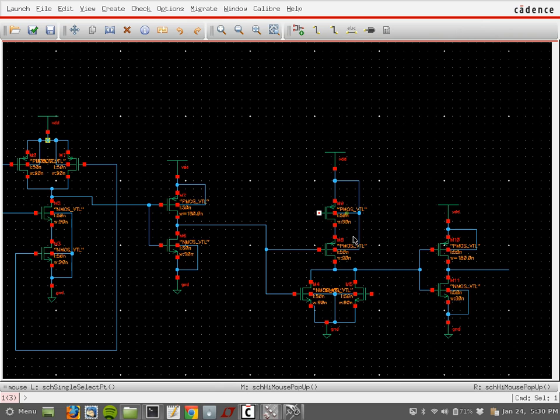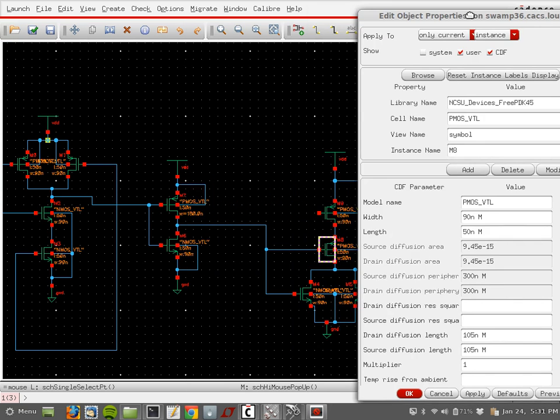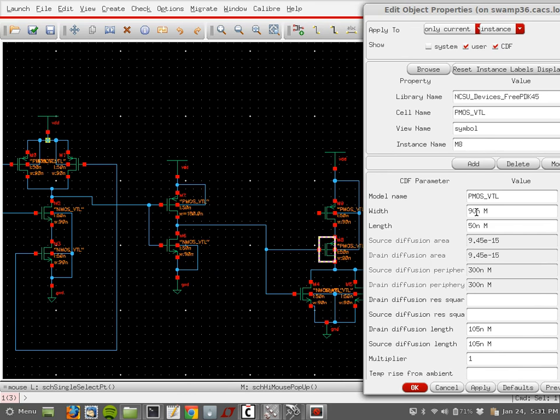But in this case, the pull-up, remember the propagation time? RC, 0.69 RC? So this is equalizing the rise time and the fall time propagation. So we have to equalize them. In order to equalize them, let's make this one 180.